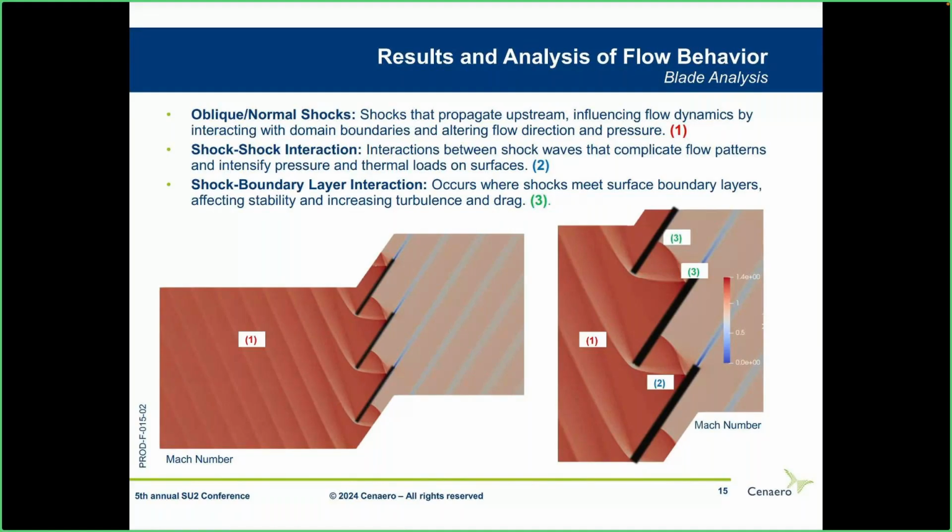What would have been great is if VKI had given me the experimental setup, then I could have just accelerated the flow to find the same value. But in my case, I don't have that, so I'm forced to go with the supersonic inlet. And it seems that in SU2 the supersonic inlet, or at least the non-reflective condition, does not support supersonic velocities. And this ties into my comment.